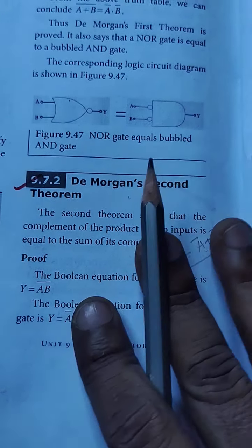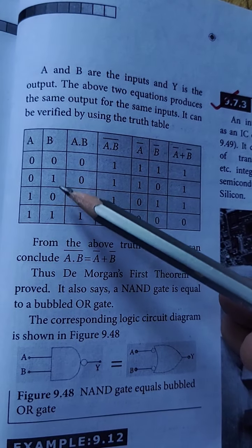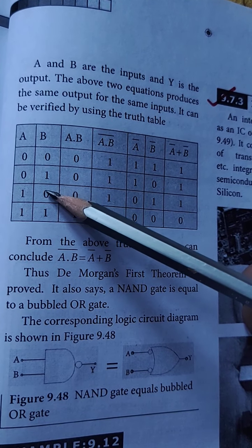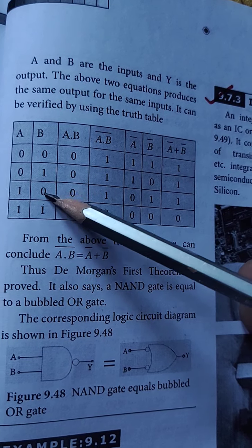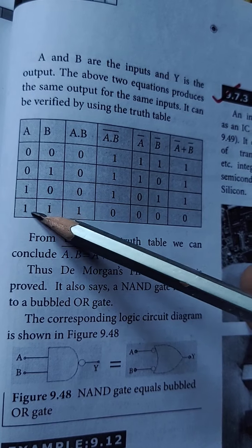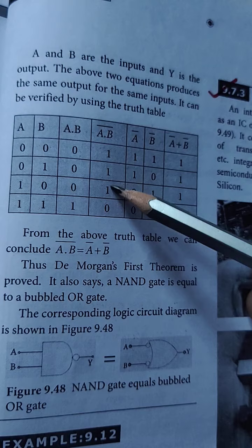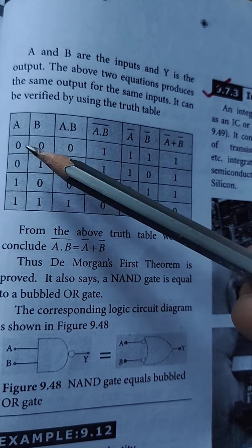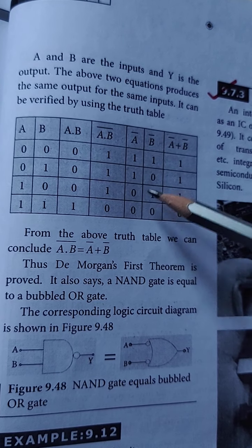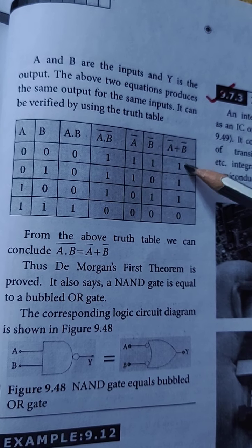In the same way we can prove it by using a truth table. For A B, the same way, for the product, if any logic level becomes 0, the product must be 0, we know that. For the last one, the two logic levels are high, so the output becomes high. Taking the complement, 0 becomes 1 and 1 becomes 0, and taking the complement of A and B respectively, we get the values of A bar and B bar. So adding these two complements, A bar and B bar, we get the value here.